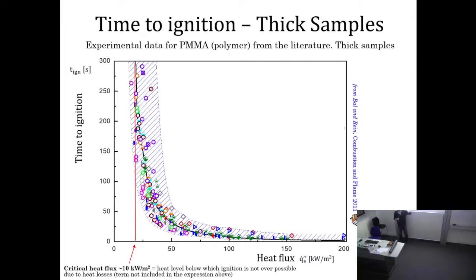So you can see flame spread, which we're going to see later on, as a series of consecutive ignition steps. The heat flux that leads to ignition when you have flame spread is really high, and you actually have ignition within seconds. And if the fire starts to grow, then more heat is arriving at the different locations, and you start to have accelerated fire behavior because the time to ignition of the next ignition layer is shorter.